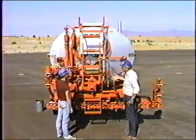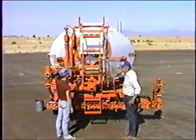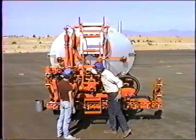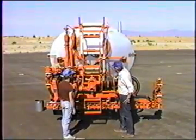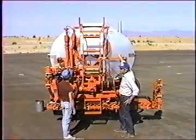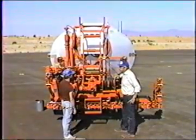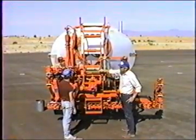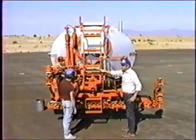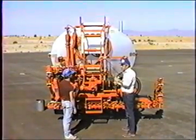The heat tube is an immersion tube. It's immersed in the asphalt. It's this 8-inch pipe that goes in from the burner, goes forward, makes a loop in front of the tank, comes back, and exhausts out the tank, out the top. That tube gets very high surface temperatures. When we fire that burner, the surface temperature will be as high as 1500 degrees on the heat tube itself.